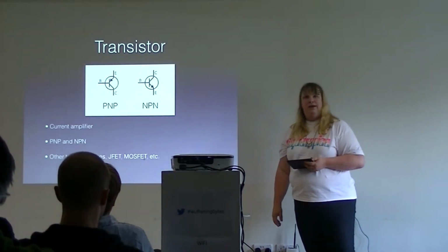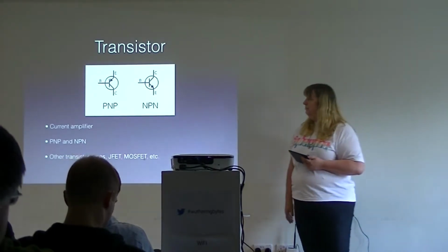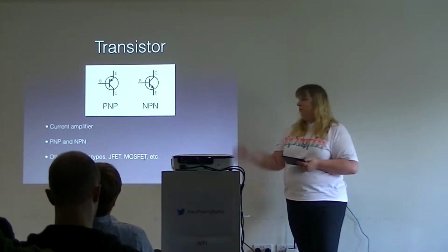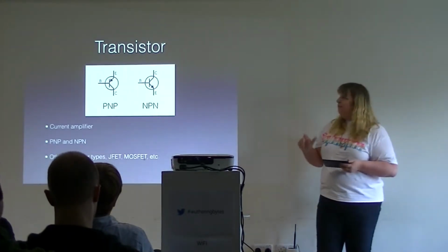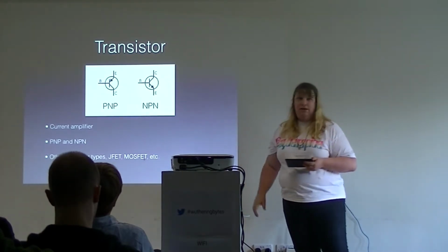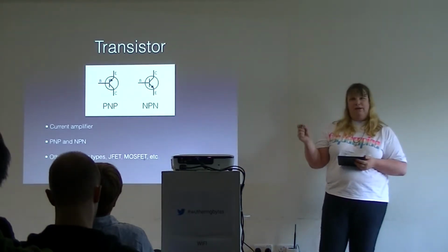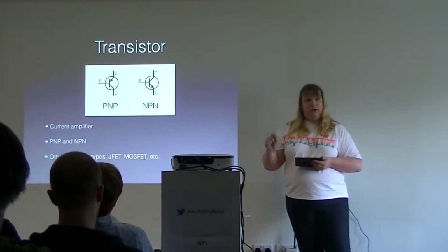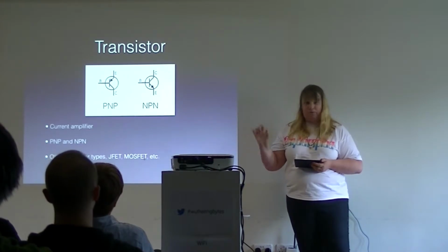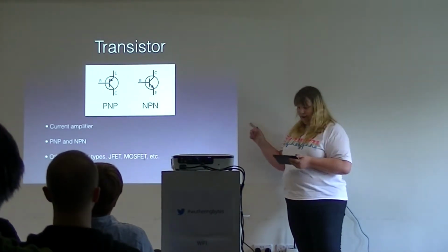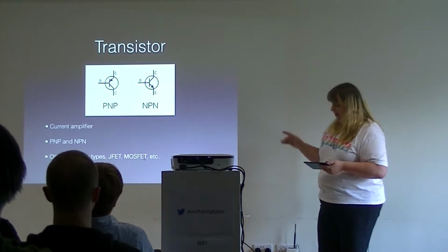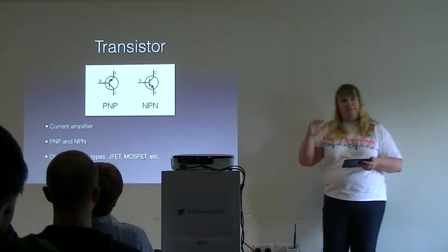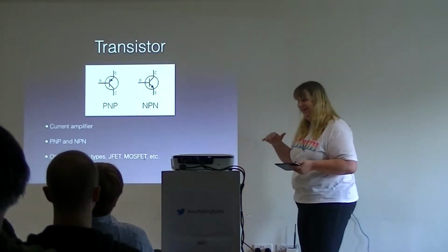Final thing, transistor, current amplifier. You can use it as a switch, which is probably what you were doing interfacing. I'm not going to go into lecturing about building Class A amps or anything like that. But basically we're interested in small transistors that you can use as a switch. So that if you've got a GPIO pin and you want to control something that uses more current than the pin can support, you can use a transistor, and I'll show you in a bit later. So, now I've whizzed through that, I can slow down a bit because I can now fit the rest in.